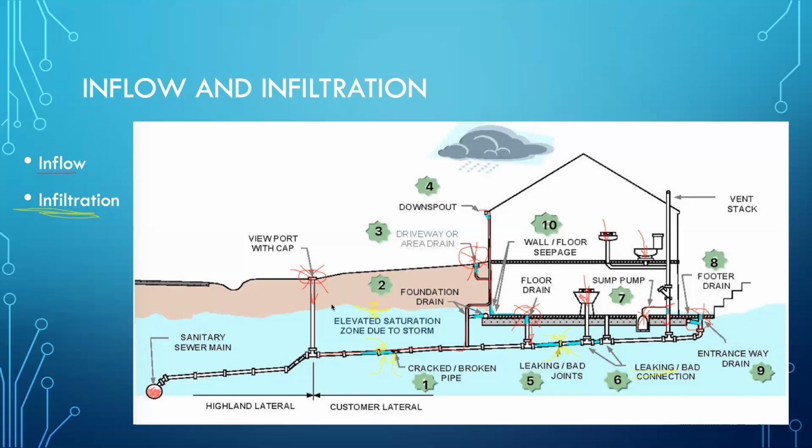And it was clear to me from the drawings that it was intended to connect to a different part of the subdivision. And somehow nobody thought to pile up concrete bags in it and close it off for the later expansion, which was years later. So they had a terrible time making their treatment plant work because they kept getting too much water. As soon as we found that location, we blocked it off, and then all of a sudden the system worked like it was supposed to. So that was probably the best research money that municipal utility district ever spent.